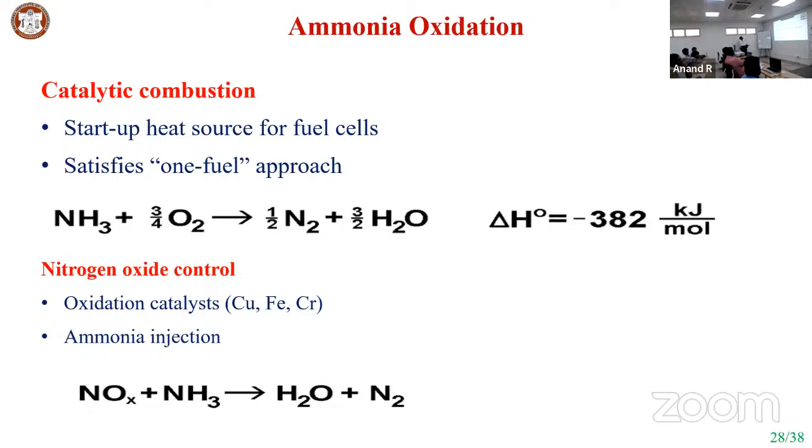So there is catalytic combustion. Ammonia reacts with the oxygen, produces water and nitrogen. By going for this reaction, we cannot avoid the formation of NOx. So is there any process in which the NOx formed reacts again with, let's say, ammonia? You can convert the useless material into useful material, water. That's also an after-treatment method. Generally, we are using it in the engine.